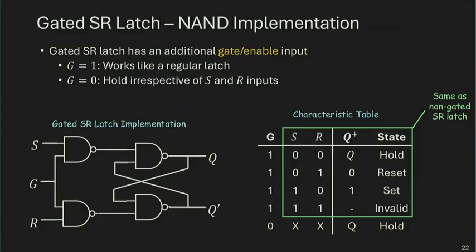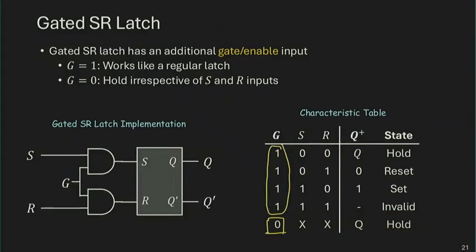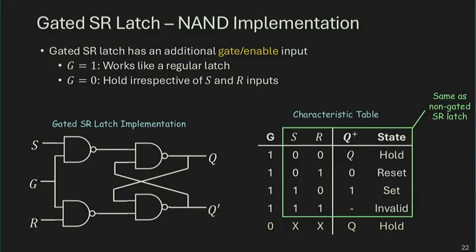And you can implement that using, again, many different ways. You can also implement a gated latch using NAND gates. What I did earlier is I assumed a NOR gate implemented SR latch together with 2 AND gates. And then when you apply some of those transformations, like De Morgan, involution, multi-level bubble pushing, you can also implement that using this kind of NAND behavior. And I invite you to also try it out. Try to plug in those input conditions, 0001, 1011, to confirm that this indeed works as an SR latch.